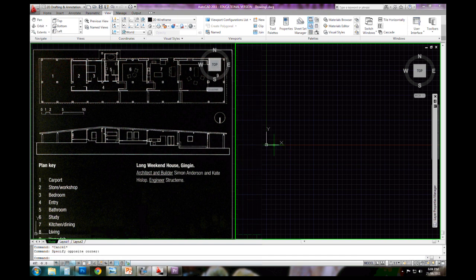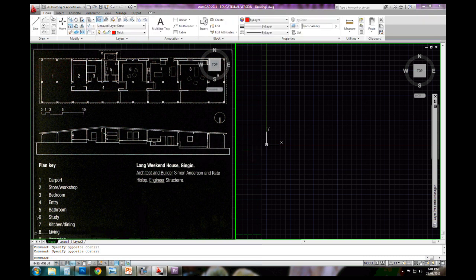Okay, so a common thing, you don't want to draw your final lines. It's the same as when you're working manually, where you'll have a series of light 4H or very light pencil work or pen work that sets up the grid for your hardline drawings, the further you go on with the project. So we're going to do the same thing in AutoCAD. A good habit is to probably draw with thin lines that you can delete, or even set up a layer called construction lines that you can turn off or delete later, and then just reveal your final work. Okay, so first line is just going to be a polyline.